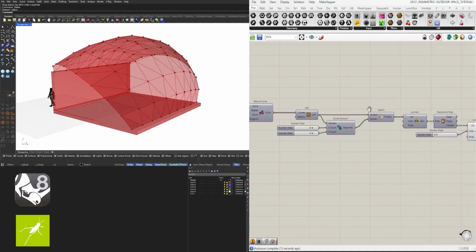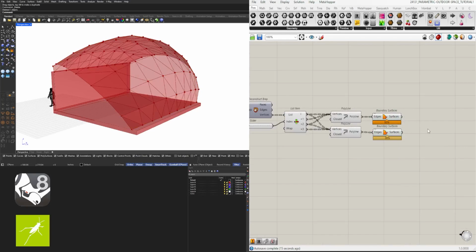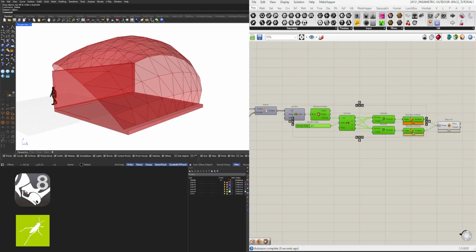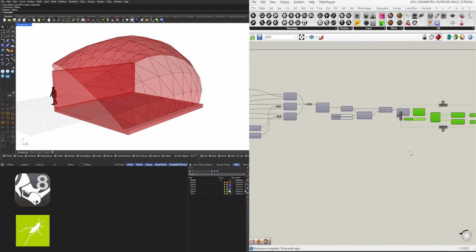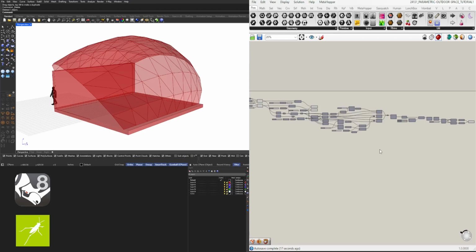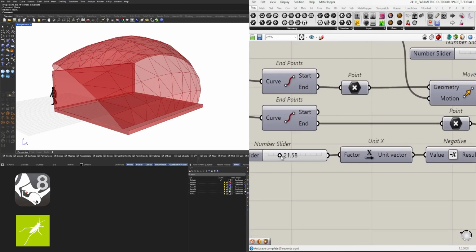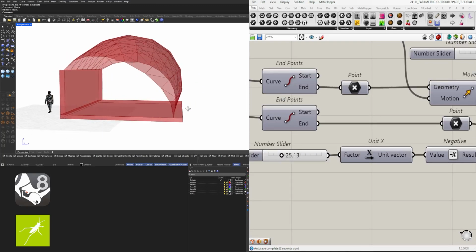Now what I'll do here is go to the end portion, take these and join them together. So I'll go to brep join. I'll plug in both of those surfaces into the input and flatten the input. This way we have just one open brep and we can hide the rest of the steps. Now what makes parametric modeling really cool, in my opinion, is that we can always change these inputs depending on what we're looking to do.